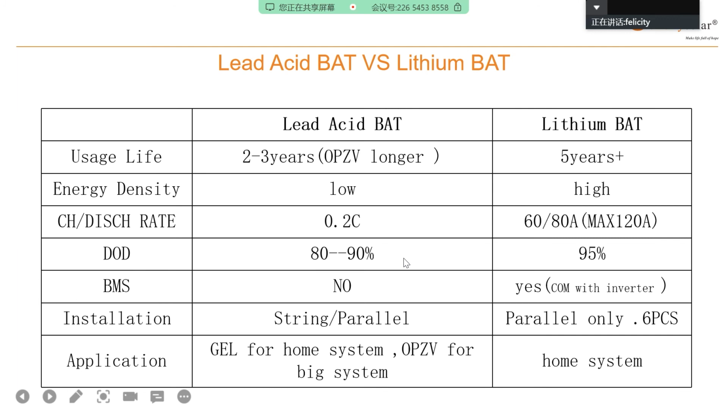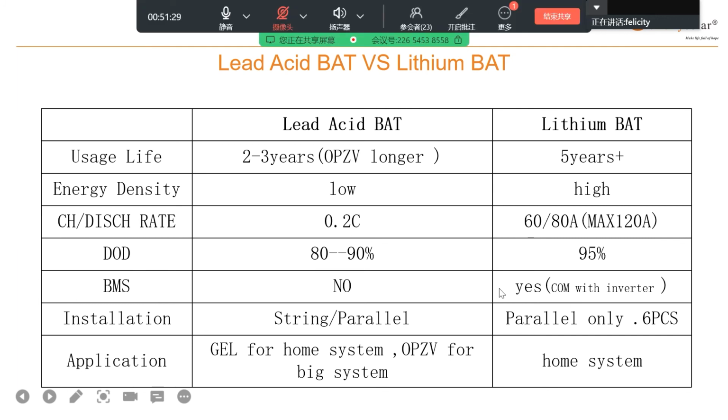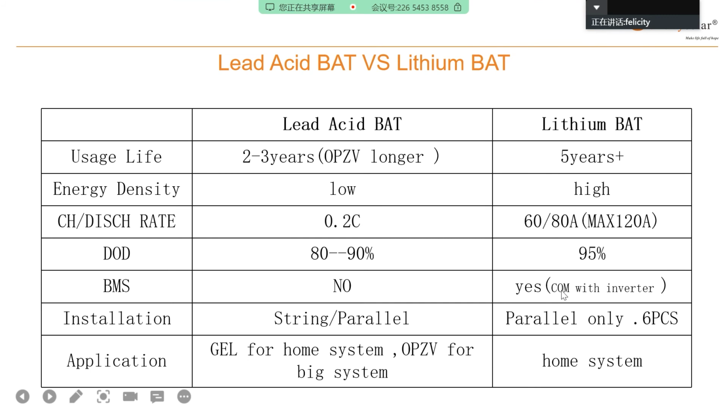BMS: lead acid battery doesn't have BMS. Only lithium battery has BMS, so the BMS can be used for communication with the inverter. Felicity lithium battery can communicate not only with the Felicity inverter, but also with other brands.